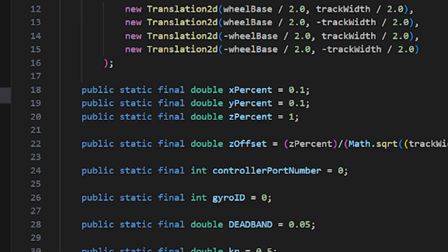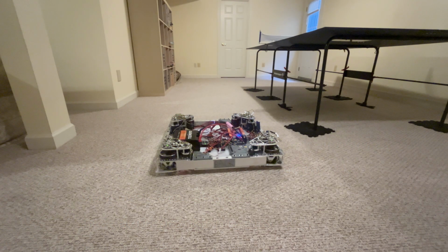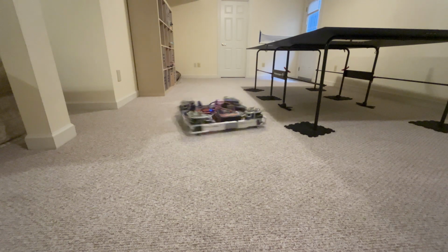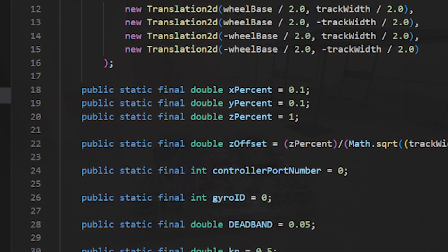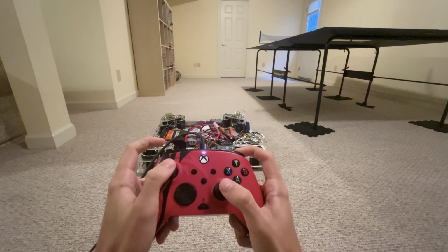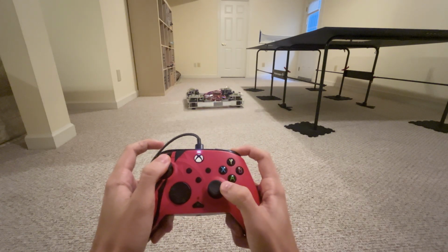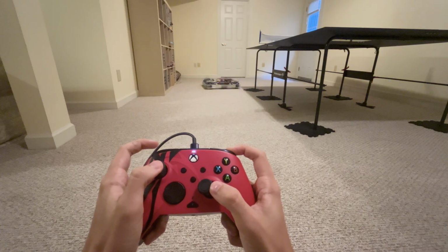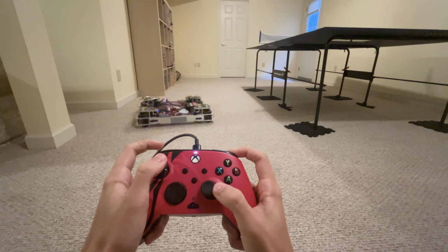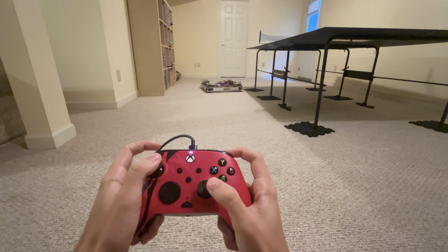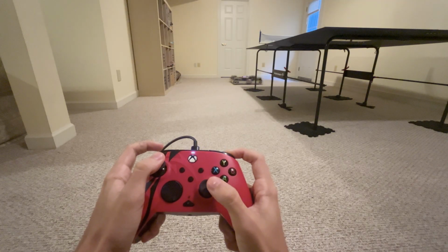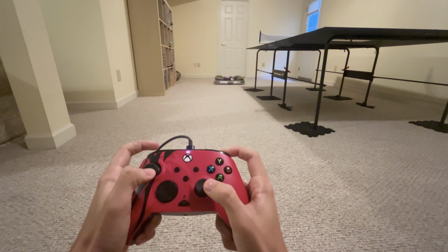Or you could set the turn to 100% and the speeds to 10%, turning your Swerve into a Beyblade. Or if you're mentally insane, you could set the Y speed to 0, hold the robot-oriented button, and transform your Swerve into a tank drive. Coding Swerve with open loop duty cycle control gives you complete power over your Swerve drive.